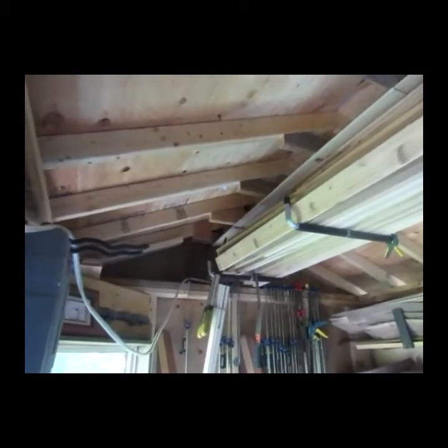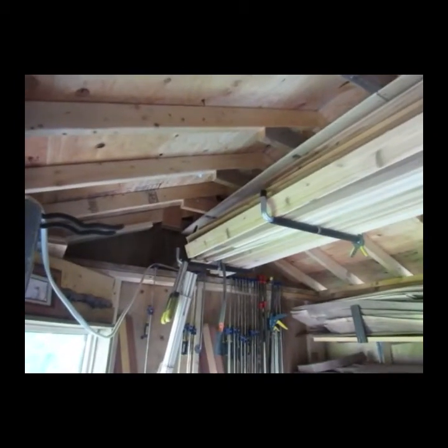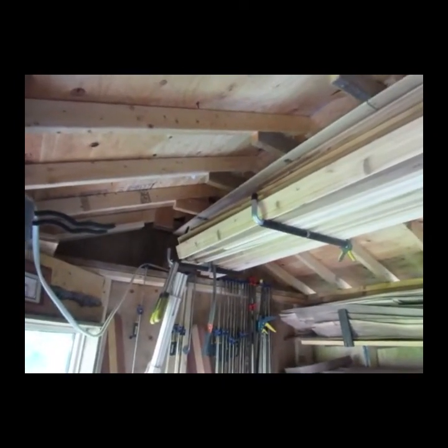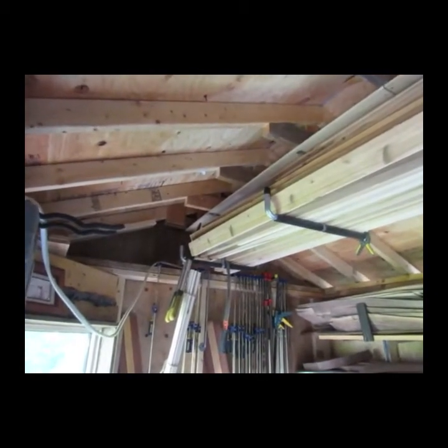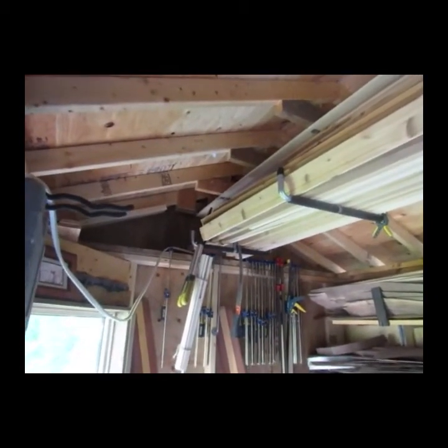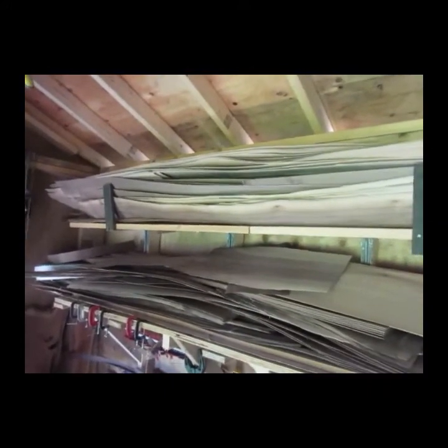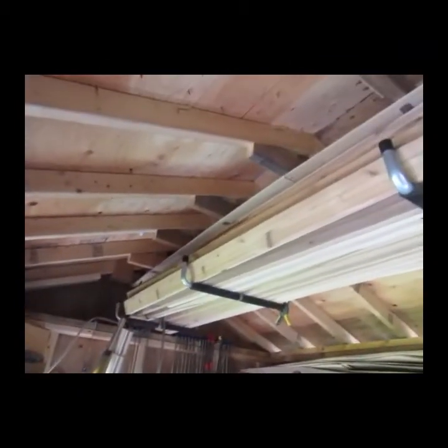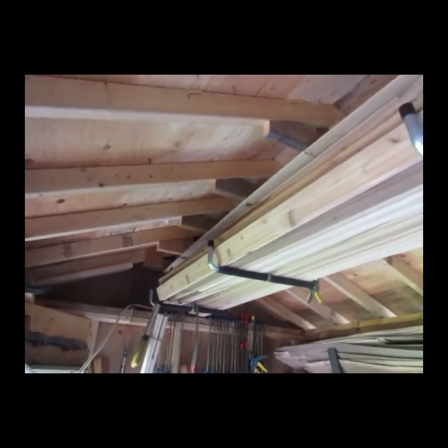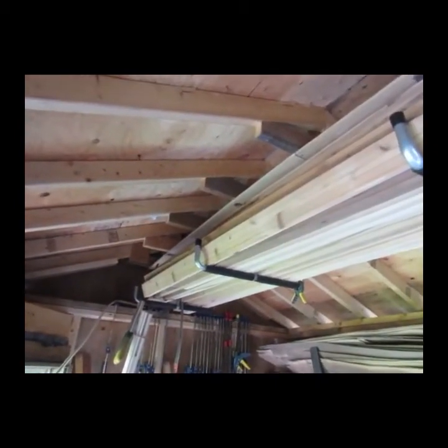That collar tie, it was interesting, and I learned something about collar ties versus what I thought I was putting up at the time, which was a rafter tie. Now a rafter tie would be a 2x4 that connects the bottom of the rafter here to the bottom of the rafter there. It's making the bottom part of the triangular shape of a truss. Now the collar ties, what they do is they stop the top of the roof from being ripped off. They actually hold the peak of the roof together.